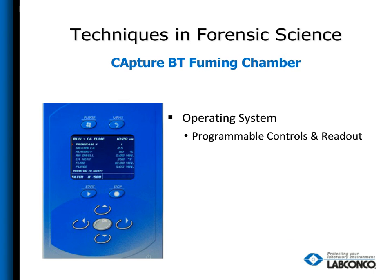The programmable operating system of the Capture BT not only displays the parameters that were programmed of the run, but also displays the actual parameters of the humidity levels and the hot plate temperatures. Knowing the actual conditions and ensuring the parameters are consistent from run to run are very important in producing the highest quality prints available. The Capture BT offers a very large temperature range. The hot plate is programmable from 100 degrees Fahrenheit to 425 degrees Fahrenheit.